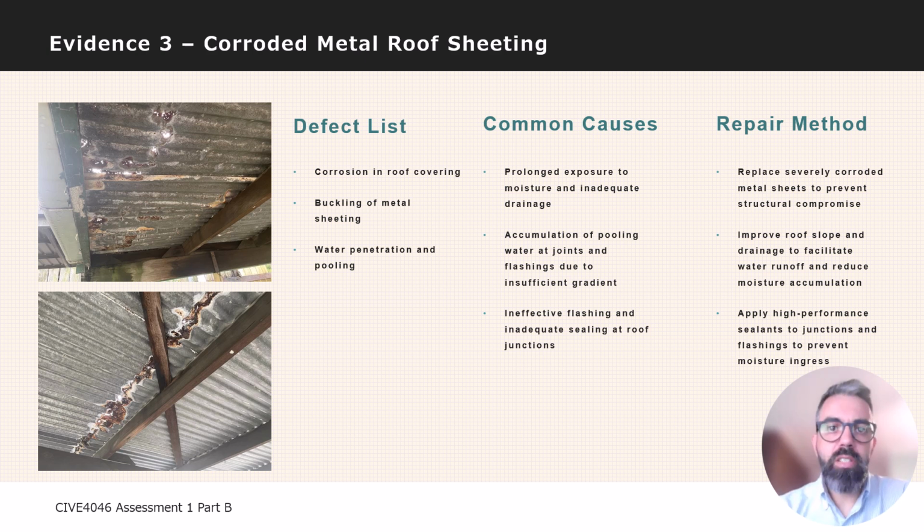The third area assessed is the roof covering, where our visual inspection revealed rusting along the sheet metal joints, bracket panels, and potential pooling water caused by insufficient slope. This defect is classified as a system intercomponent failure, as it involves the degradation of roofing materials due to combined thermal, moisture, and mechanical stress.